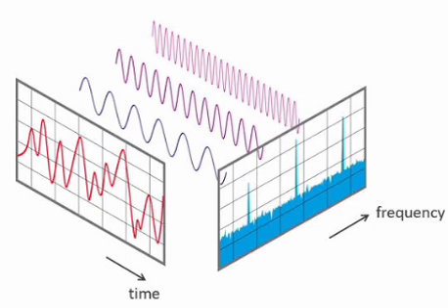cos(ω₀n) u[n] ↔ (1 − cos ω₀ z⁻¹)/(1 − 2cos ω₀ z⁻¹ + z⁻²), |z| > 1. sin(ω₀n) u[n] ↔ sin ω₀ z⁻¹/(1 − 2cos ω₀ z⁻¹ + z⁻²), |z| > 1.